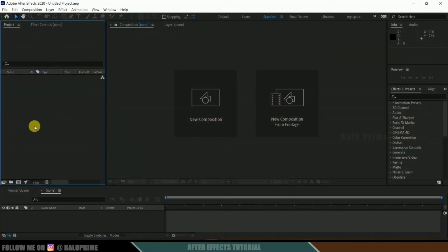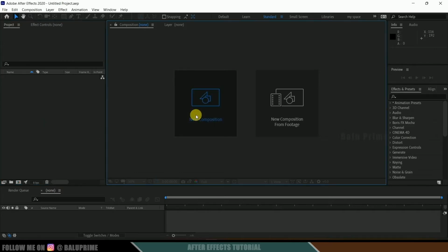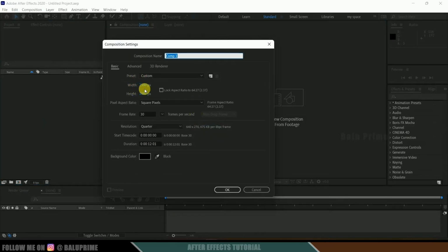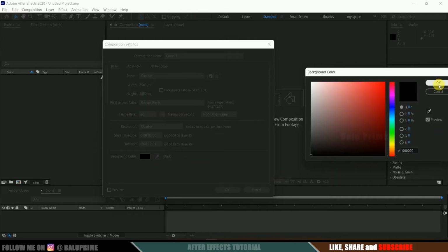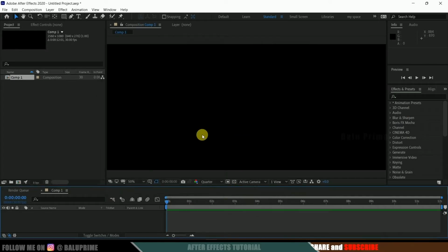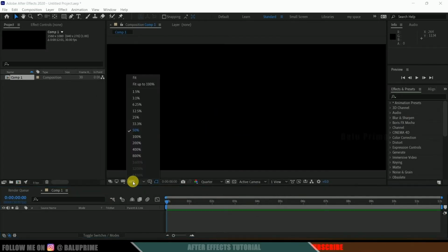So here we are in After Effects. Now let's start this by creating a new composition. So for that, simply click on this new composition. Here I will be using a resolution of 2560 which is a widescreen or 21:9 aspect ratio with a frame rate of 30 and duration of 12 seconds. And background color, let it be black and hit OK. So here we got our composition. So let me make it fit.